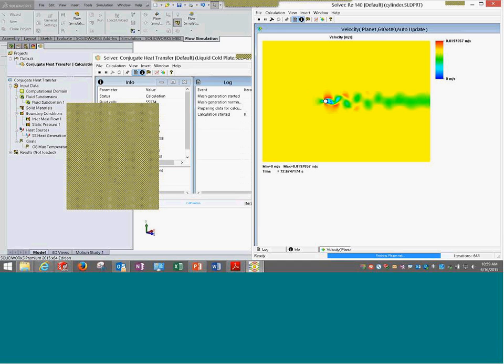Couldn't automatically consider. First of all, there is nothing called automatically considered. So it is not there. Yesterday I showed you the option of the wall boundary condition. Using the real wall boundary condition on the external walls, we can manually give a convection value over there. If it is not given, then it is treated as an adiabatic wall and no heat transfer happens. That's the way it works.